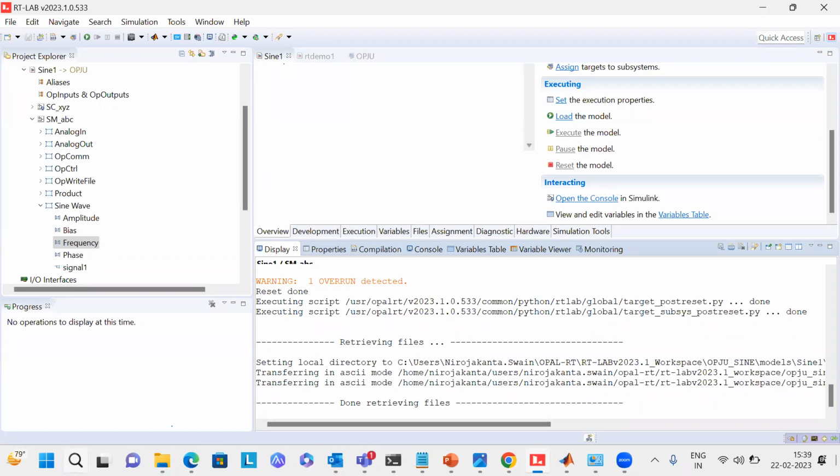Sir, I have one doubt. Suppose when we are running the inverter, generally our sample time is 10 microseconds, 20 microseconds like that. If I want to run the model for less than 1 microsecond, maybe in the range of nanoseconds, it will not run for that. If we run in FPGA using the EHS block, I have seen one example model actually, but I could not understand it very clearly. That is the reason I'm asking.